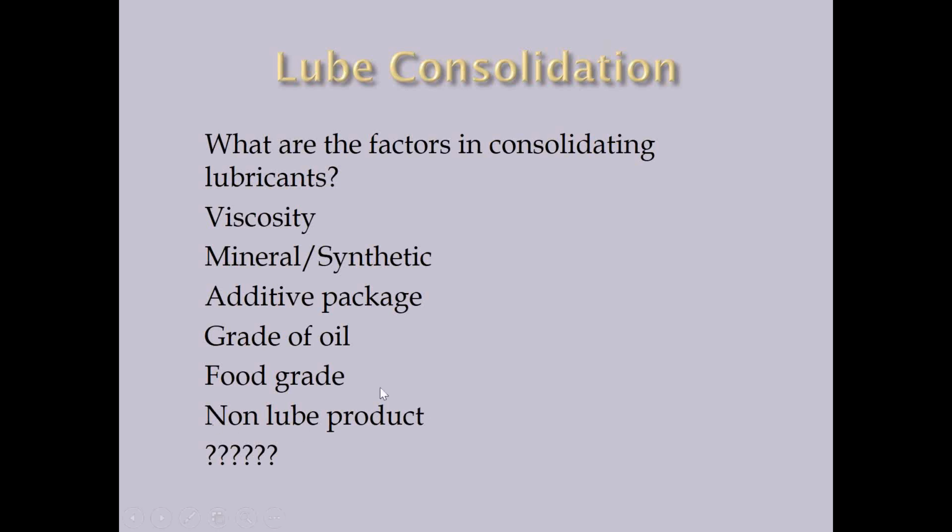Me and my son go to plants all the time where they're using the same filter system to filter antifreeze or coolants as they're using for their lube oils. Sometimes when you're consolidating, make sure you don't have any non-lube products in there. Whenever we're consolidating, we have to ask all the questions to make sure that our consolidation process is not going to ruin the lubes we have.